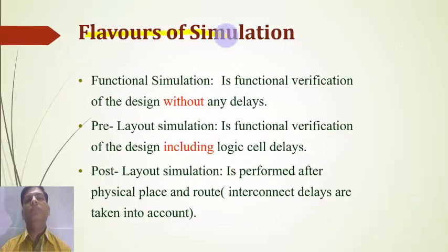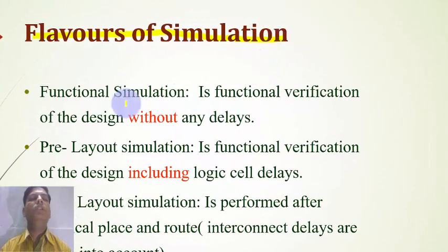Flavors of simulation. Functional simulation is functional verification of the design without any delays. Then pre-layout simulation is functional verification of the design including logic cell delays.